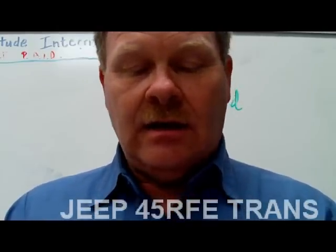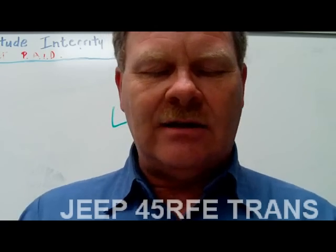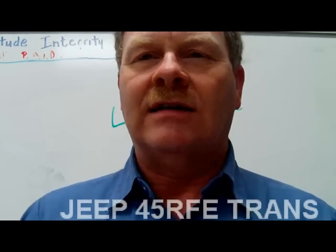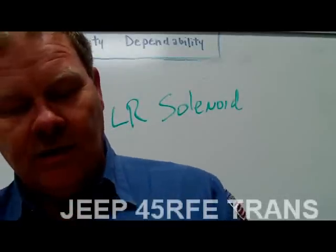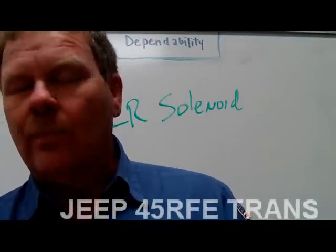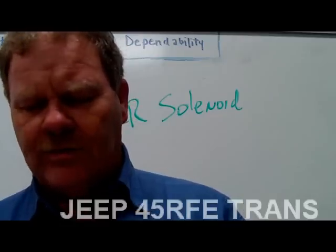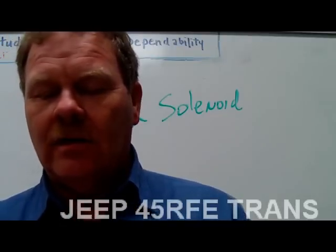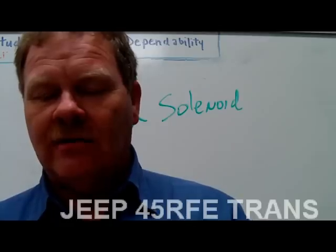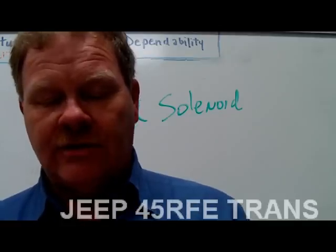Now then, since the 4RFE is electronically controlled, the diagnosis of suspected transmission problems is going to lean toward the electronic side as well, and you're going to use the DRB scan tool or equivalent. Now, the use of the appropriate manual plays a key role. Okay, we're going to whip through this right quick. Clutch volume index, it's what I was talking about before. If you've got a clutch volume index that's a little bit high, it shows the fluid fill volume of each clutch circuit.